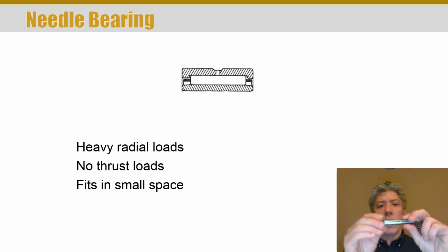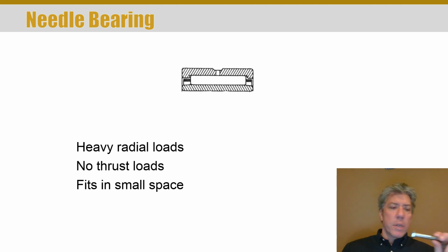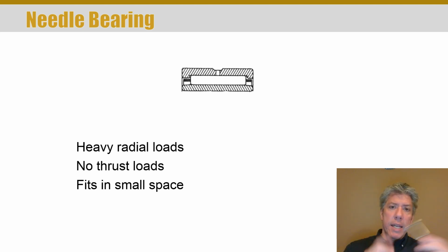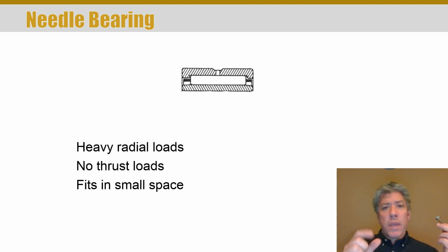Well, some actually are. The problem is, as we're going to talk about later, the inner and outer raceways have to be made very hard, because there's going to be fatigue of the materials, which you're really concerned about. Every time a rolling element comes around, it doesn't matter if it's a ball or a cylindrical element, the contact is theoretically either a point or a line, so the stress is theoretically infinite. In other words, the rolling elements flatten out a little bit, and the raceways flatten out a bit as well.